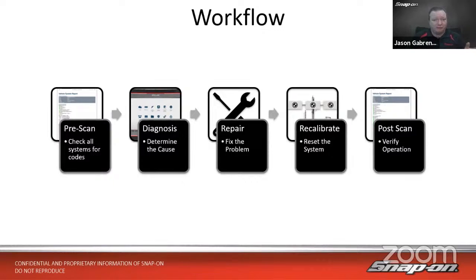That's coding the injector to the vehicle. Sometimes maybe you replace a throttle body, you need to do a throttle body relearn. Another popular one is 06 and newer GM vehicles. When you replace the oxygen sensor, you need to reset the heater circuit on that vehicle. Otherwise, it will burn out that oxygen sensor heater circuit, usually in the first few hundred miles.